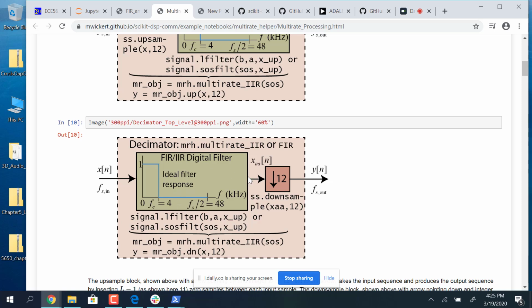And the kind of nice thing about this is this low-pass filter in the demodulator that's sitting in the decimator can serve the purpose of the low-pass filter that you ordinarily have in a coherent demodulator. In other words, this low-pass filter will prevent aliasing, and it will also make sure you get rid of the double frequency terms.